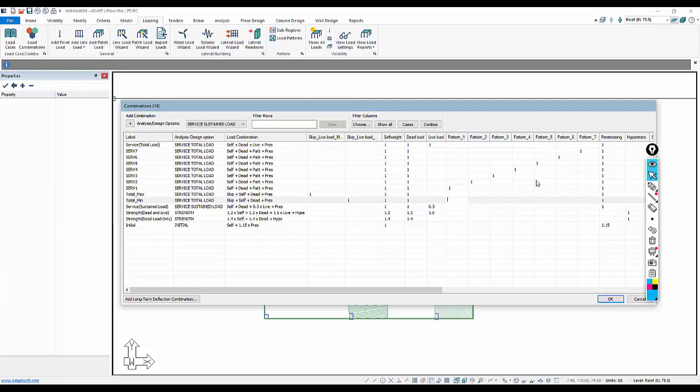Now it may not make sense to actually set up both entries. In other words, if we already have to include these patterns for example, for deflection, we may not have to include these. The only reason you would want to include these is because if you look at contour deflections, you would actually have to go through and look at each individual result based on the pattern, whereas if you use the skip max min, you only have to see that once or twice for minimum and maximum. So in other words, we don't overlap and envelope the contour results graphically. So this is how we would set up the model for the purpose of evaluating contour results. It's not only deflections, it could be moment XX, moment YY, in-plane axial forces or stresses, and so on.